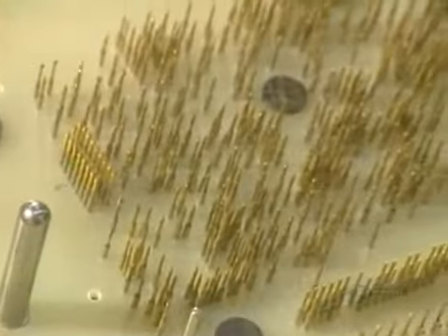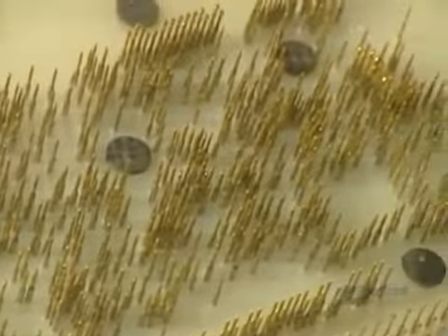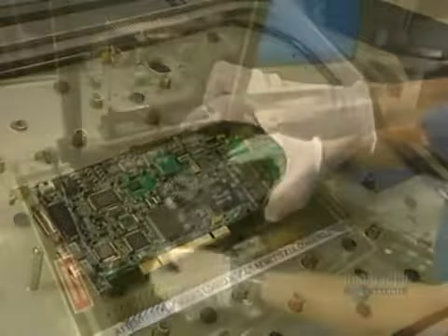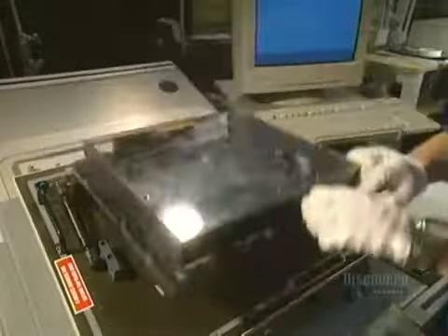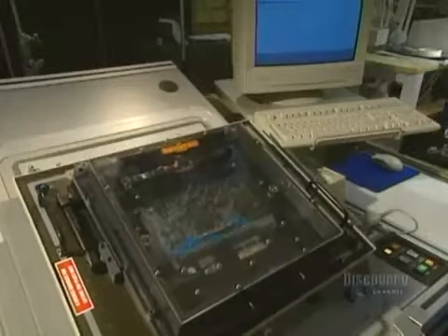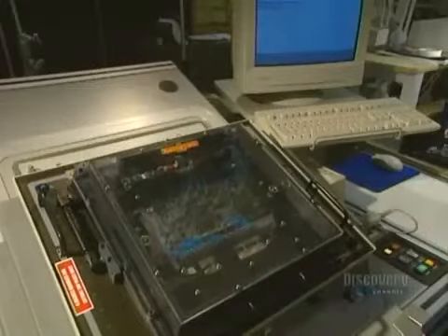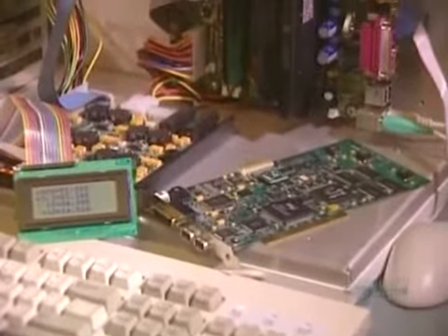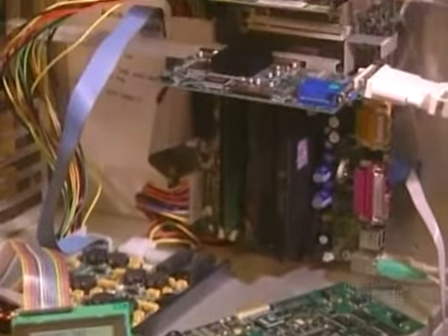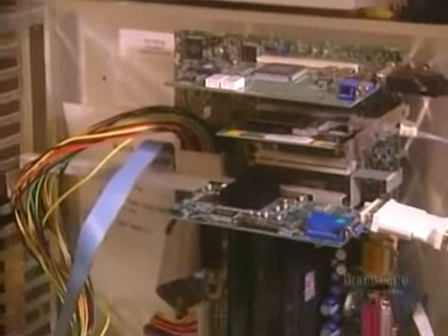Now, everything is installed. They have to do an initial electrical test. The card is placed on a bed of electrified pegs. These pegs make contact with the card's connecting points, allowing them to check for short circuits or open circuits in the card. And then a final test, a computer-aided operating test to see if the card is functioning perfectly.